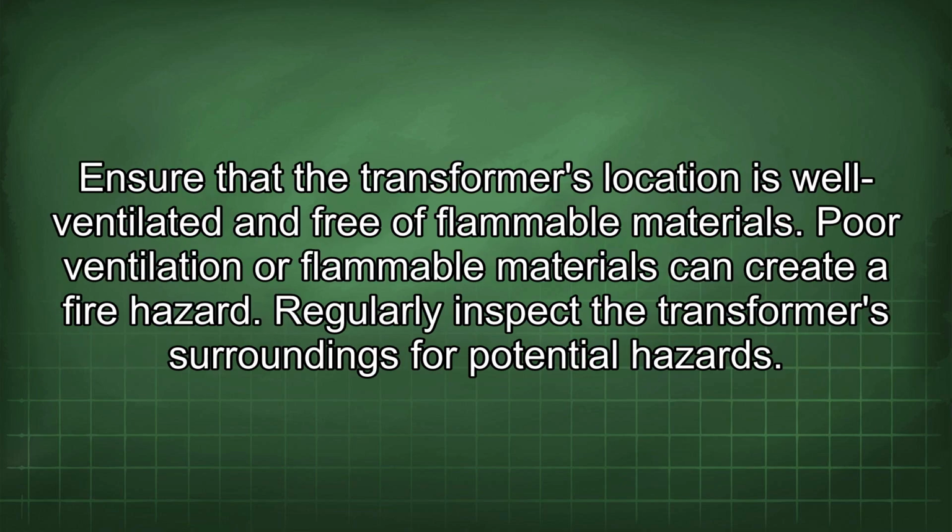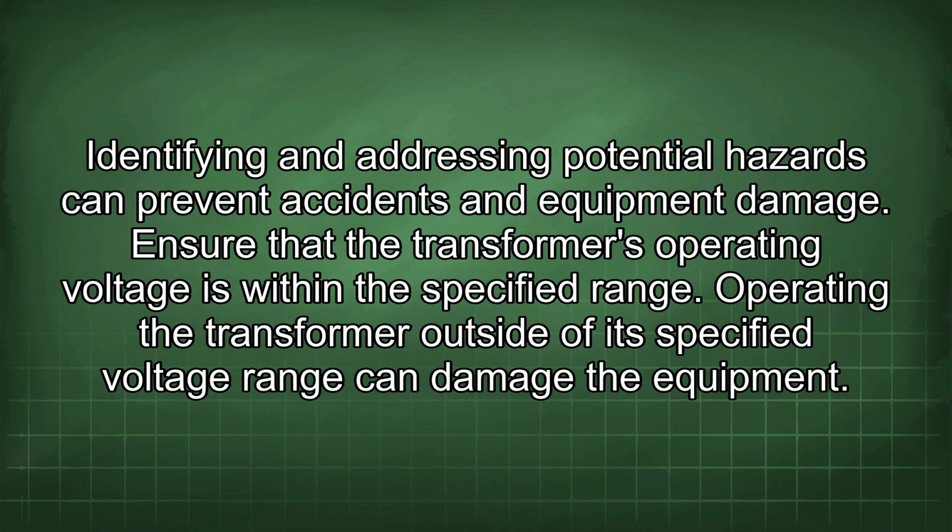Ensure that the transformer's location is well ventilated and free of flammable materials. Poor ventilation or flammable materials can create a fire hazard. Regularly inspect the transformer's surroundings for potential hazards. Identifying and addressing potential hazards can prevent accidents and equipment damage.